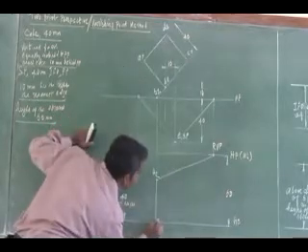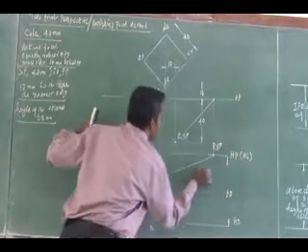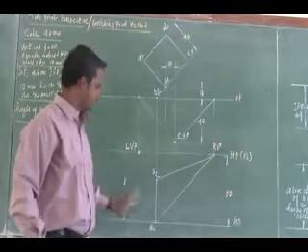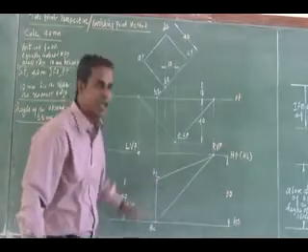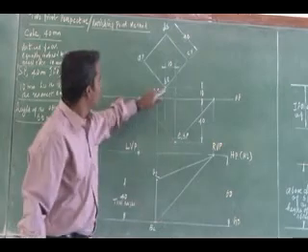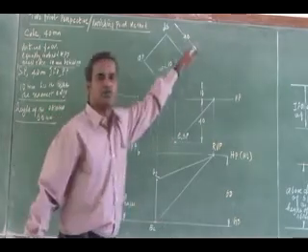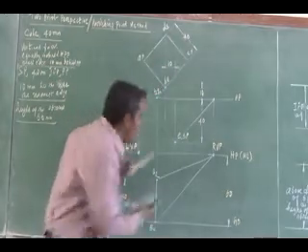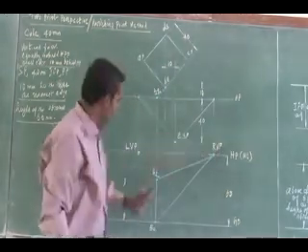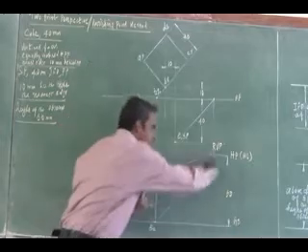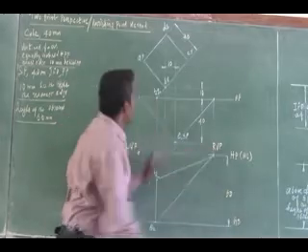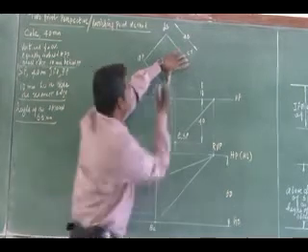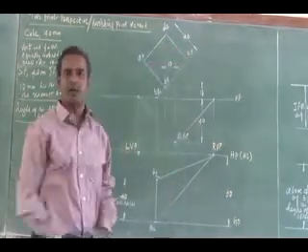This is a vanishing line corresponding to B2. Are you clear with this? So I have drawn B2Q2. I am drawing two vanishing lines for this face to get the perspective of this face, because this face is going to vanish at the right vanishing point. So B2Q2 marked down. Within these vanishing lines, I have to get the perspective view of this face BQCR.